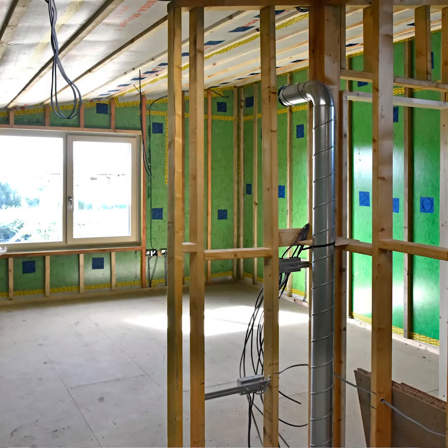Studs are placed either at 450 or 600 mm centres. This means that they are 450 or 600 mm apart. Good builders use 90 by 45 studs at 450 centres, as this makes a home stronger and gives it a more solid feel and sound. In this image, you can see that we've used 90 times 45 studs at 450 centres.